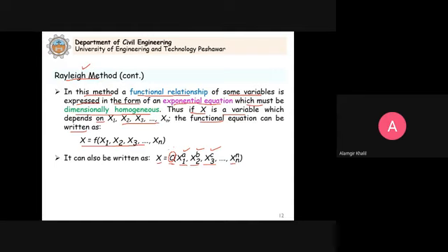So that's why we put it here, because we don't know the exact relationship and the dimensional analysis cannot provide the direct relationship. The solution is partial only. That's why we need to multiply here a C. And this C must be determined experimentally. Dimensional analysis cannot calculate this C for you. I will consider some cases that you are familiar with, that we studied maybe in the fluid mechanics 2 course. So we will apply the dimensional analysis. You will then understand that dimensional analysis provides a partial solution, not 100%.